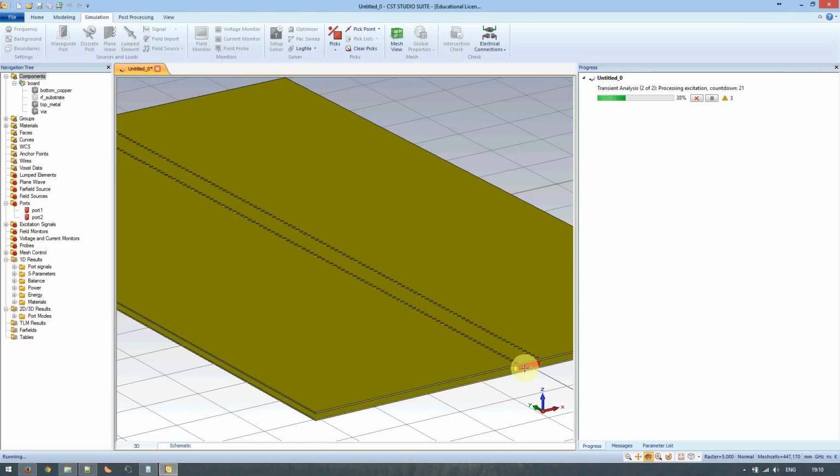So the modes that are not passed or not propagated generally bounce back and forward inside the waveguide. The transient solver works by putting in a signal at the front and seeing how it comes out at the end and at the front again if there are any reflections.